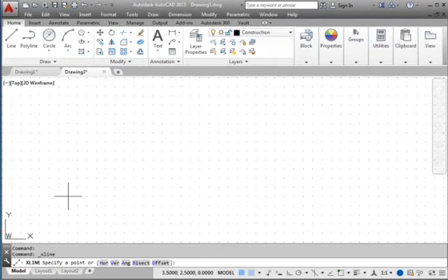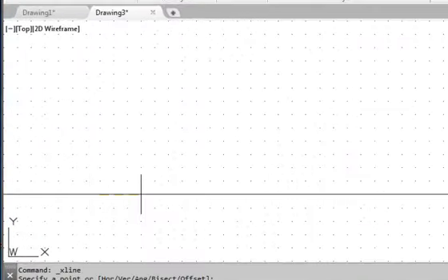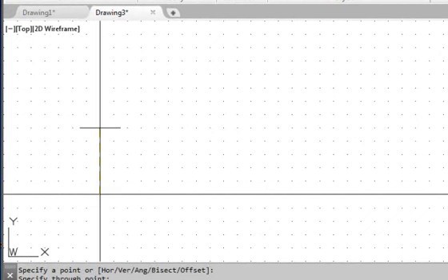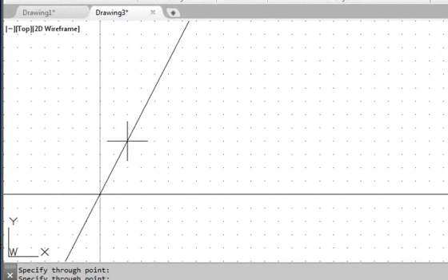Again, it is not necessary to use the origin of the world coordinate system as a reference point when creating designs. It is one technique we can use. We can create our design in AutoCAD without aligning to the origin. We will first create a horizontal line and a vertical line near the bottom left corner of the screen. These two lines are used to identify the lower left corner of our front view. Hit the spacebar once to end the construction line command.